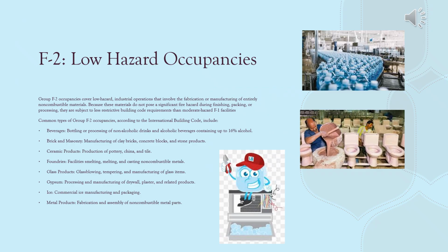F2 is described in the IBC as your low hazards. This is going to be a place that manufactures something that's not quite as combustible. Think about china, tile, concrete products, different things like that.